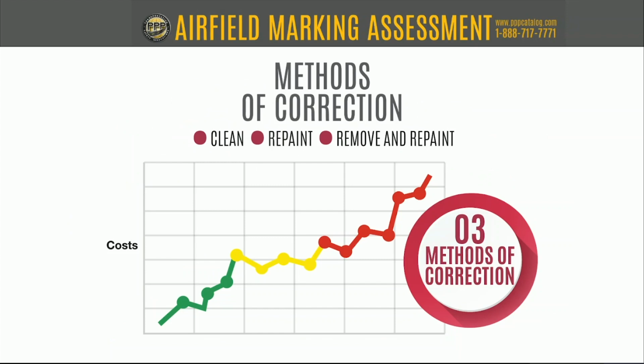I will say that cleaning comes with a big caveat: it has to be installed well initially in order to even have a chance to clean it. If it's not installed well, let's say you have non-uniform markings or poor embedment, those beads are sitting high in the paint. Cleaning with maybe a pressure washer, but if you have an ultra high pressure water blaster or a high pressure water blaster, something like that can actually take those beads completely out of the paint, and now you are into repainting, which is not what we're looking for.